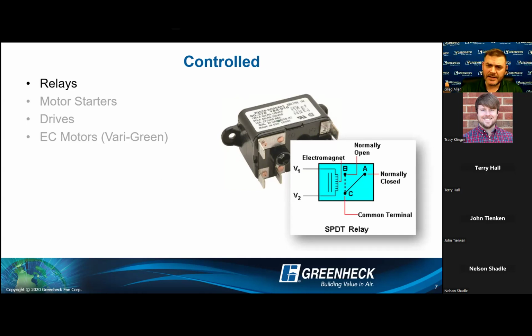activated, it's going to change state for the normally open, normally closed terminals, right? So really, if we look at this diagram, I am accepting a wet or voltage signal, and my output is continuity between B and C or A and C, depending on whether I'm activated or not. So now I can change paths. If A and C are connected, this happens over here. If B to C is connected, this happens over here.